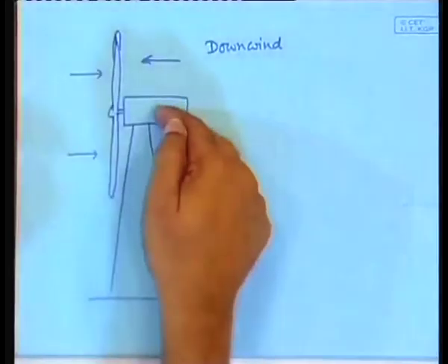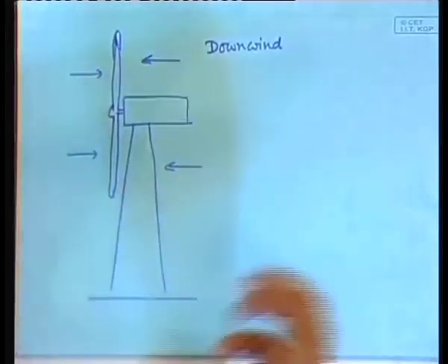So, the whole thing works as a system, and it is not necessary for each one to detect the direction of the wind, because all of them will face the same wind from the same direction. So, there can be just one place where the wind direction is sensed and the signal is sent to all the wind turbines to do the orientation. In that case, there will be a central controlling station from which the control is actuated.